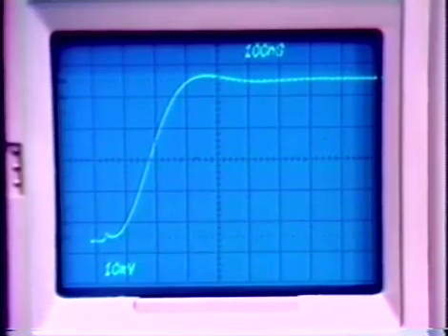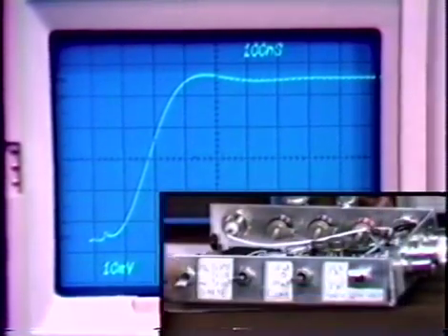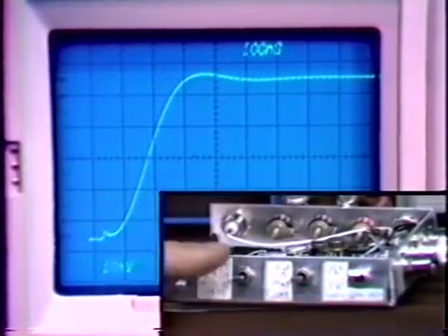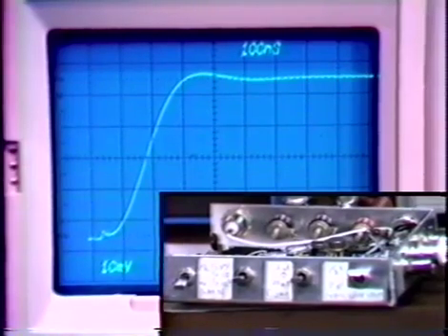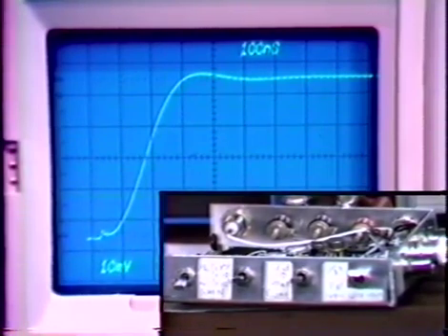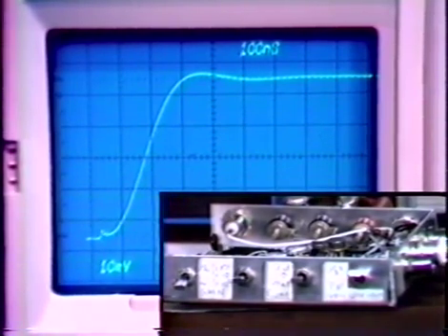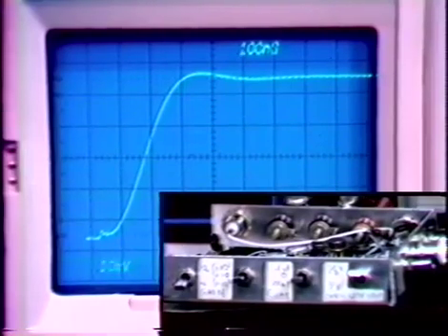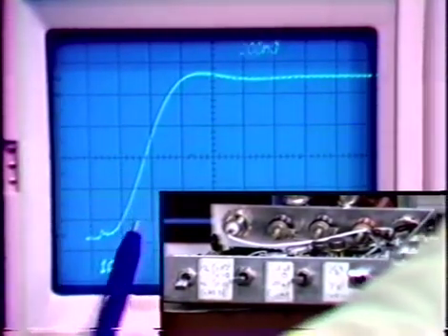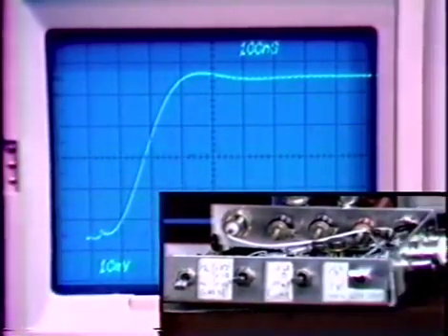The switches on the front of the box, in particular these two switches, allow us to change F, thereby establishing different values for the ideal closed loop gain. Right now we're set up for a closed loop gain of 1 with F equals 1. As I mentioned earlier, we have the 20 picofarad capacitor, and we're looking at the resultant step response.